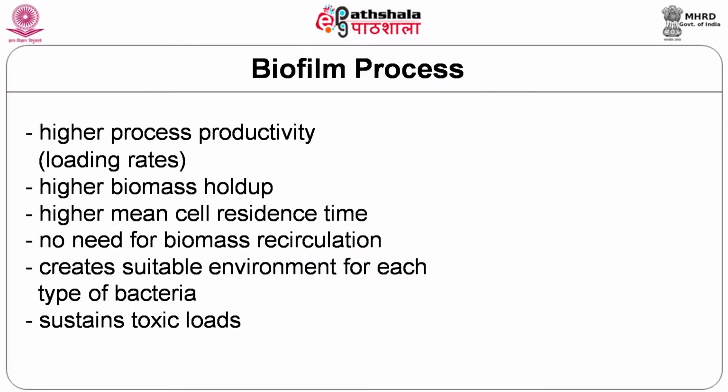In all these cases, the beneficial organisms are suspended in the aqueous phase. So, these organisms will move here and there throughout the reactor. They will take substrate throughout the reactor. While designing the configuration of an oxidation ditch as well as an activated sludge process, we have to keep enough turbulence to avoid concentration gradient along space. But here the fixed film process or the biofilm process is entirely different from suspended growth culture.